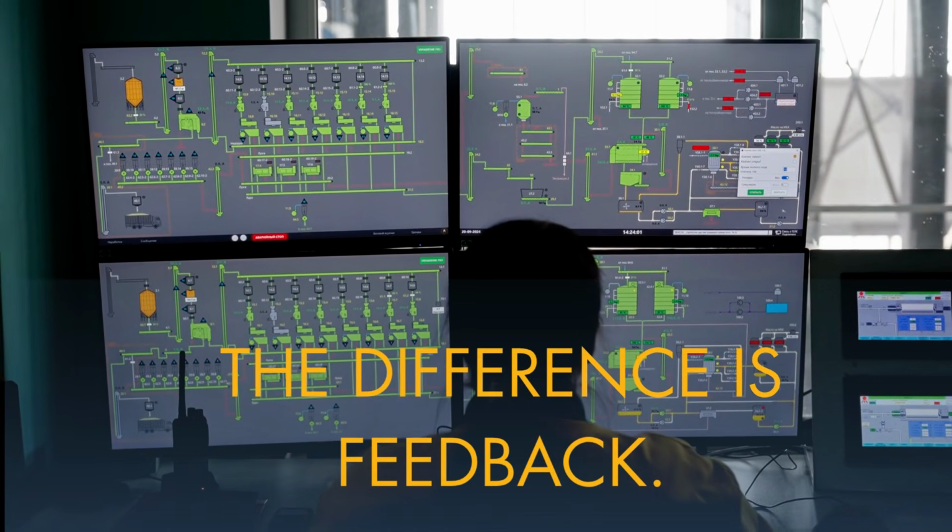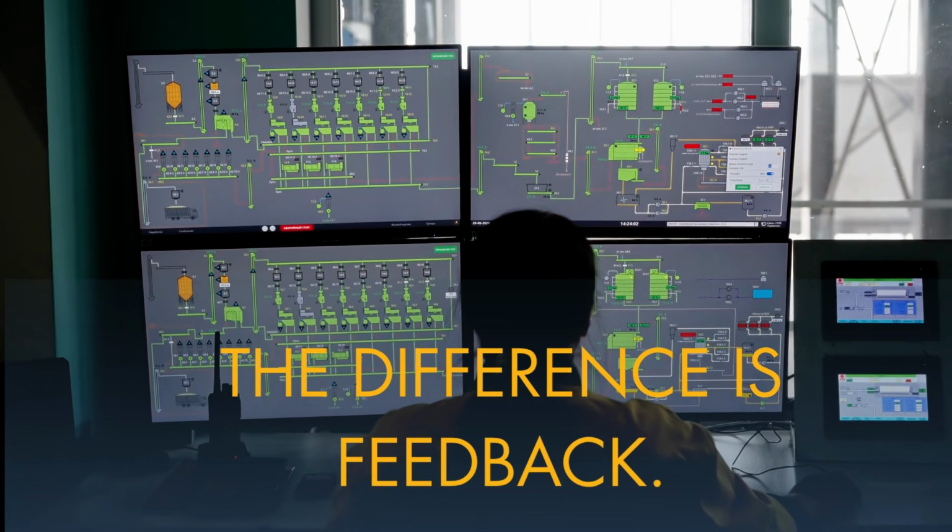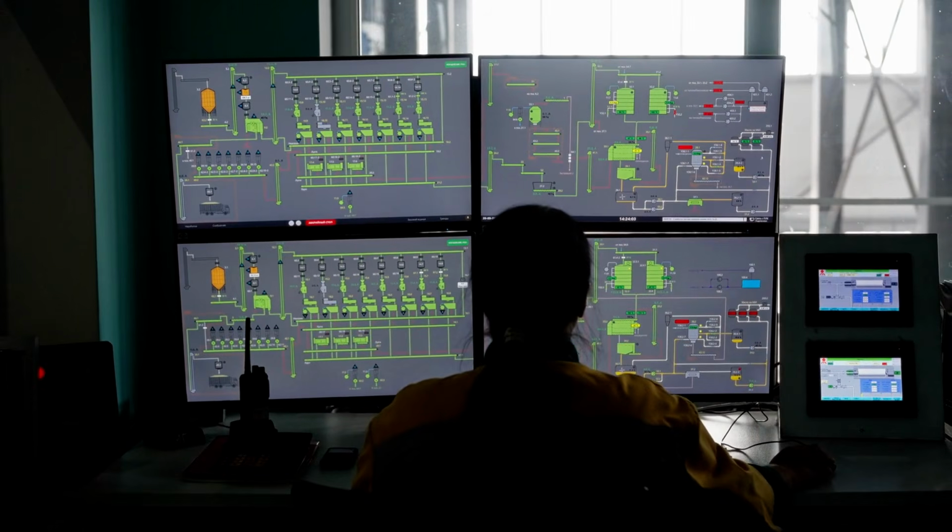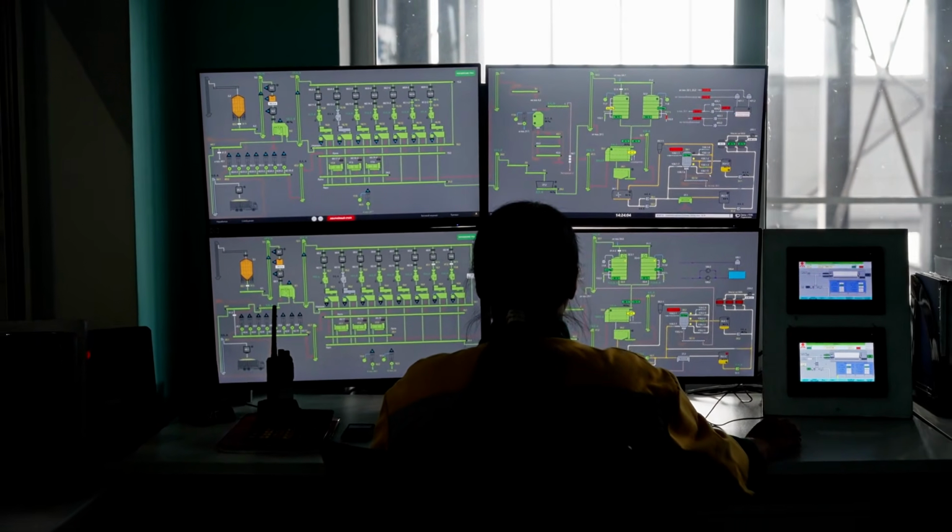The key difference is feedback. An open-loop system sends a command but doesn't use the result to adjust that command. The closed-loop control is going to look for a parameter, make changes to get to that, whereas in open loop, we just send out the signal and we don't make a correction. What we get is what we get.